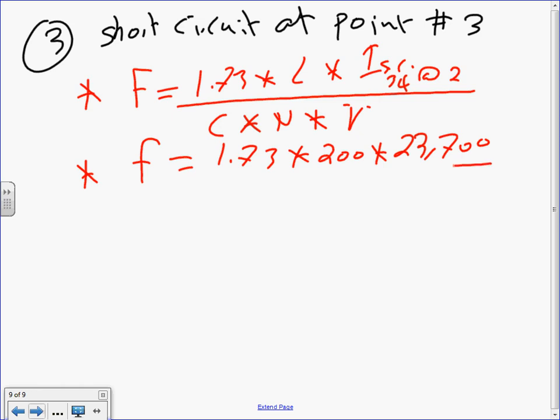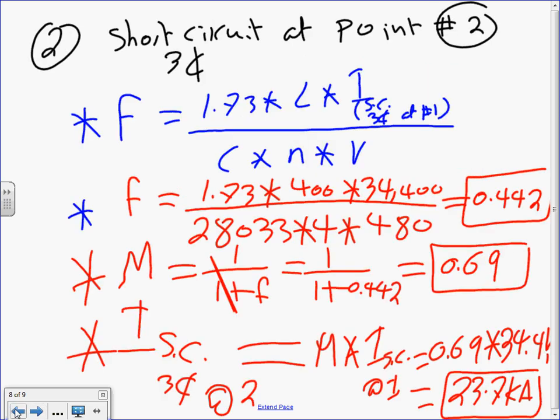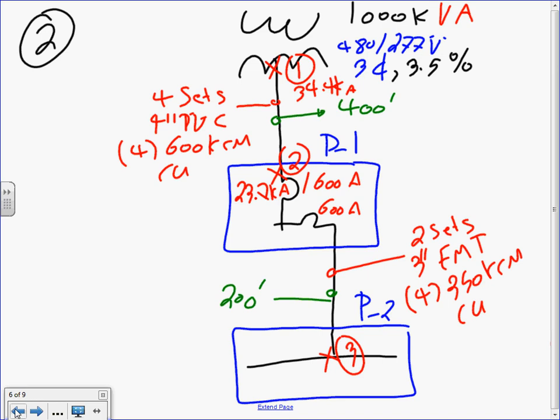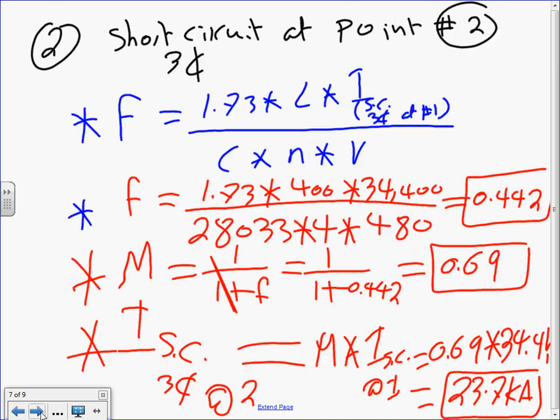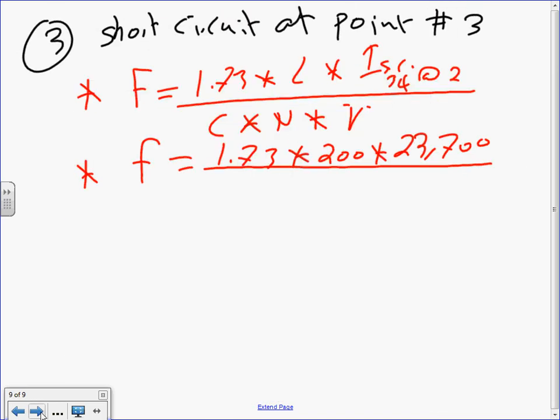Divided by, what's the C? Let's go find the C for what size conductor? We have a conductor size of 350. What's the C for 350? EMT, non-metallic, so steel. 350 steel. Anybody? 19,529. So that will be 19,529.